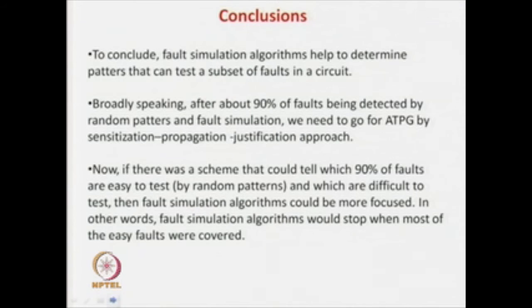We do not carry anything. For a pattern, we just find out what are the faults that are detectable in one go. That is why the fault list will have only those elements which are detectable, and then we forget everything, apply a new pattern and do it again.